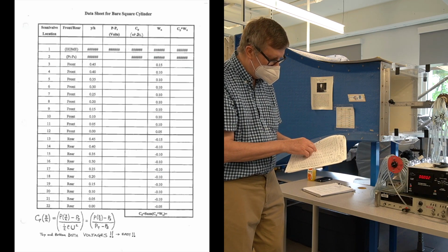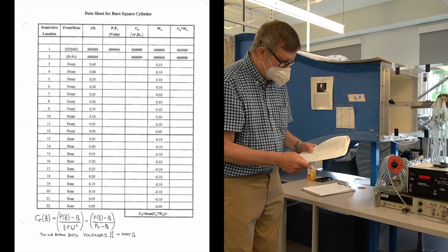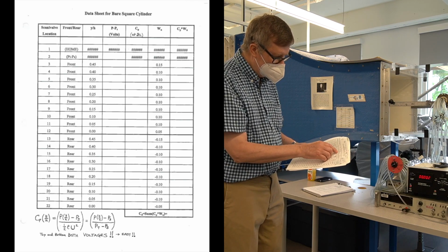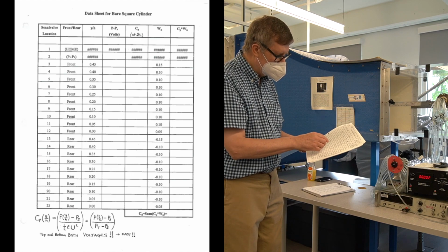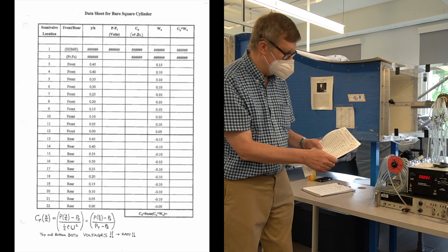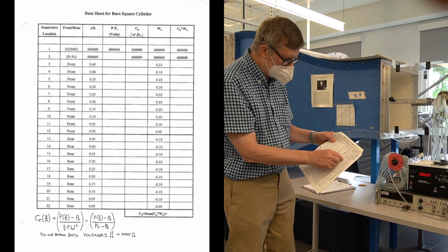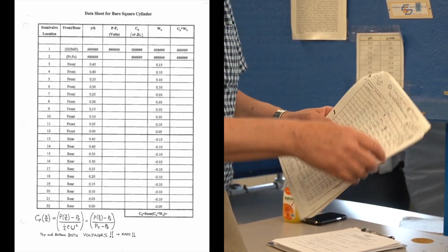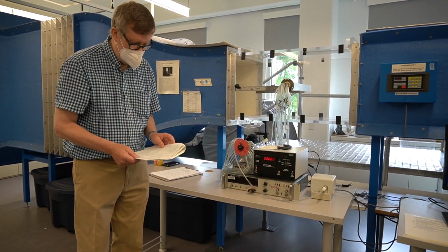Then you multiply that by y over h, the location, and you also evaluate the P minus PS or PT minus PS, going down this column here. Basically, you're trying to get a pressure times an area. You've got pressure coefficient here, and you've got the weighting function here. That's pressure times area, and when you multiply them together and add them all up, you get the total drag coefficient of this body that you're looking at in the test section.